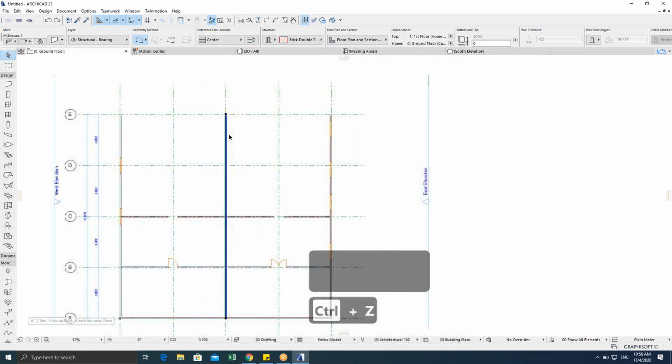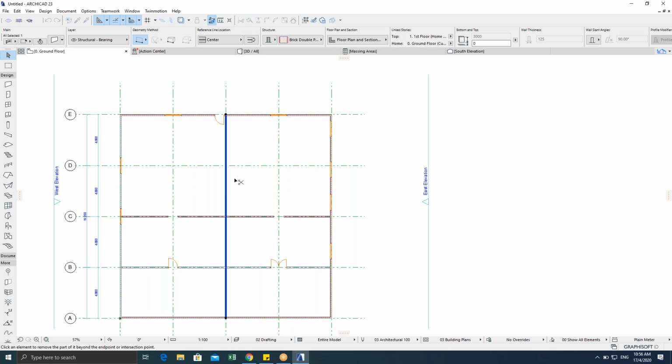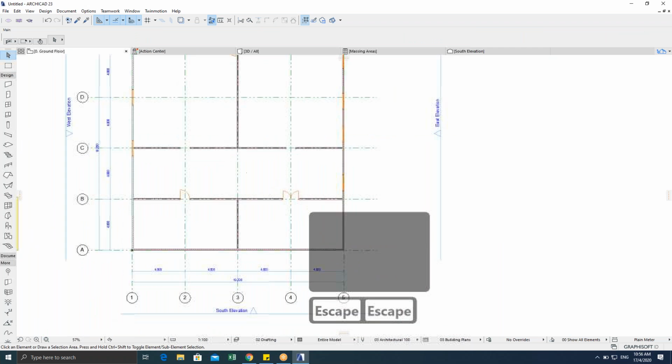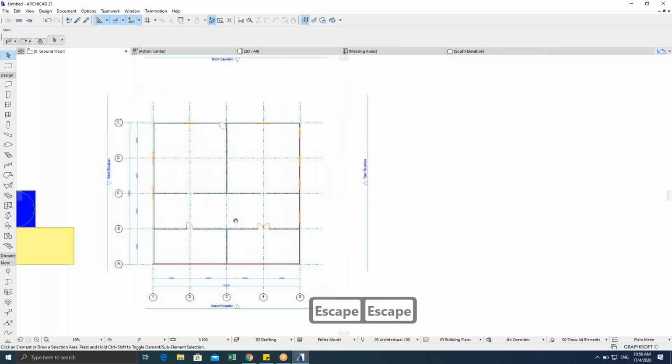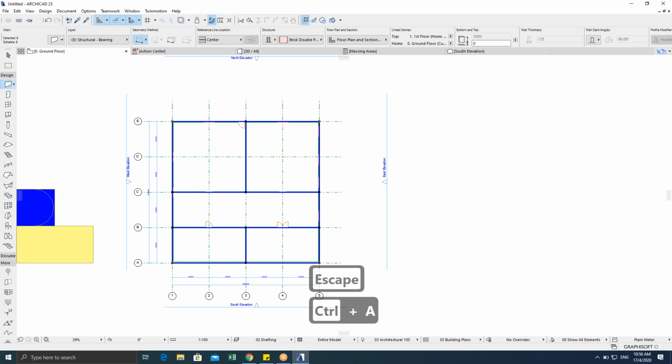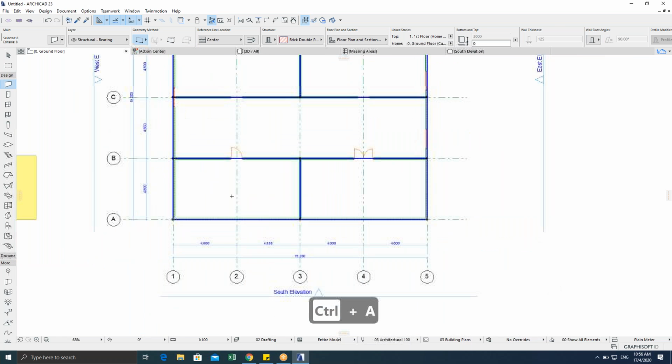Okay, now I want you guys to select the wall at the center and click this trim button, hold space, and click this area. So it's supposed to automatically cut your wall there. Of course, it's just a model. At the end of the day, I want you guys to have your model of your building. So after that, I just click this wall and Control A.